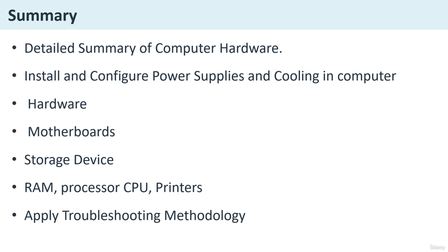Okay, now we will understand the onboard buttons and debug features. First of all, power and reset buttons. They are helpful for test benches. Second is the POST debug display, which shows error codes during boot. Third is the clear CMOS button, which resets the BIOS without removing the battery.